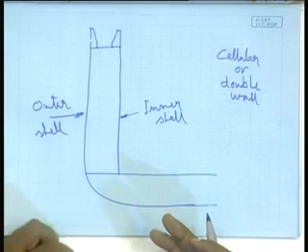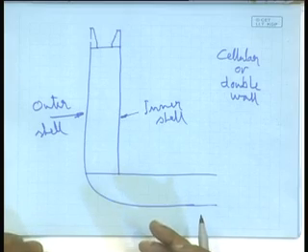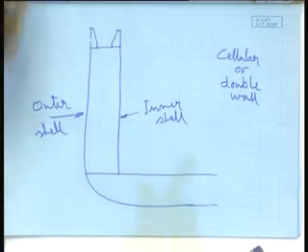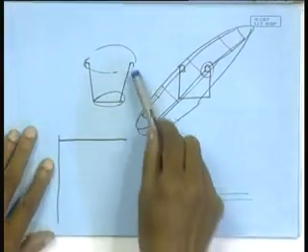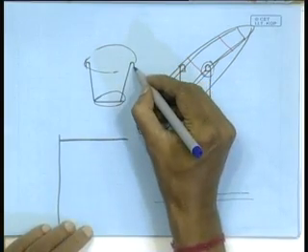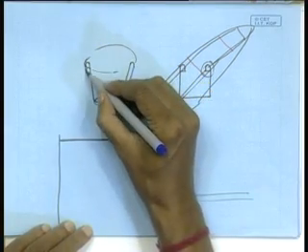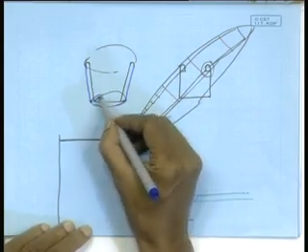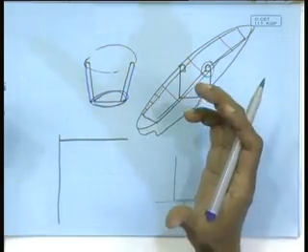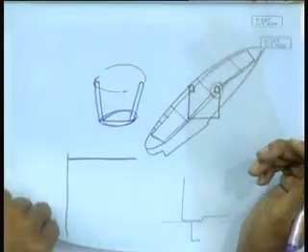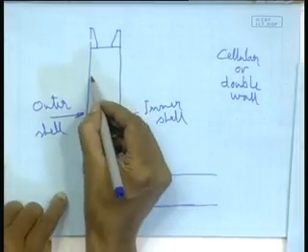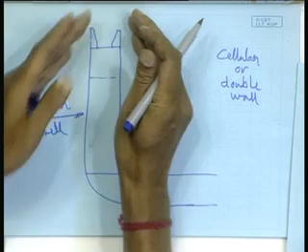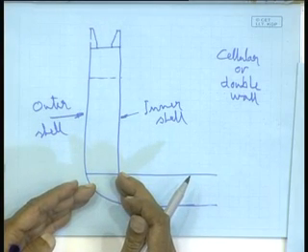Obviously, then it becomes much stronger, because if we go back to that bucket example, instead of this I make the whole thing double. If this way I could have made the bucket wall, then it will become really rigid. Same thing is happening here. So, we don't have a box girder here. As if the box thing was only this much, it has extended till the double bottom. The full thing I have extended.